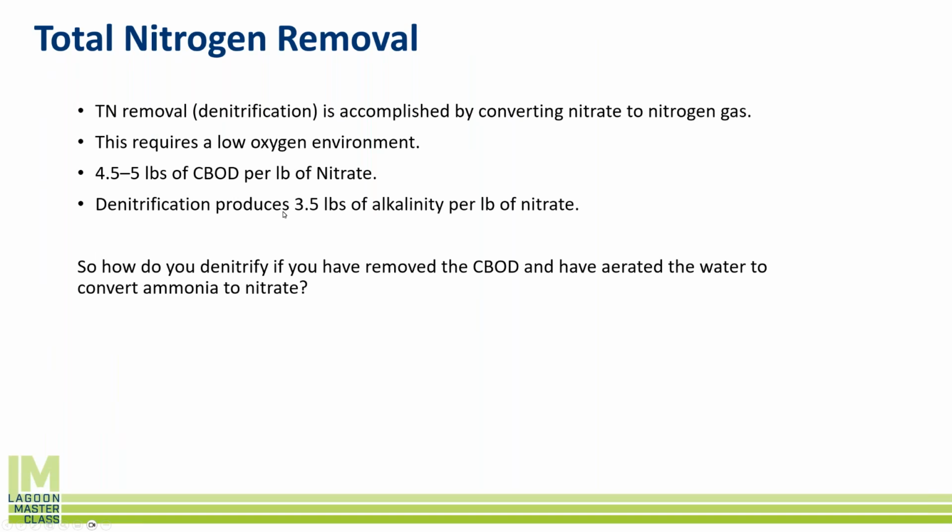And one really nice thing too is that denitrification starts to recharge the alkalinity, and it'll add some of that alkalinity back into the water. So if we need to do nitrification, we can get a recharge here and reduce any potential chemical dosage that we want to try to avoid at all costs, because chemicals are just expensive and complicated to dose in many cases. So how do you denitrify?